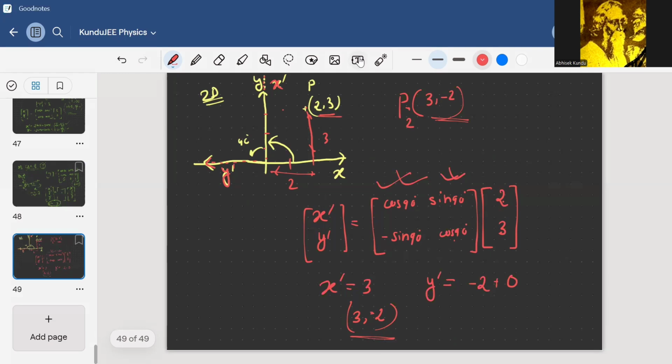But once the robotic arm is rotated, whatever data you have given becomes invalid after one rotation only. So each and every time for rotation you have to keep on multiplying with those transformation matrices in order to reach that particular point with respect to your absolute coordinate system. But of course, those matrix multiplications we will do by the program that we will write.